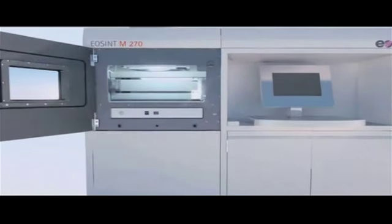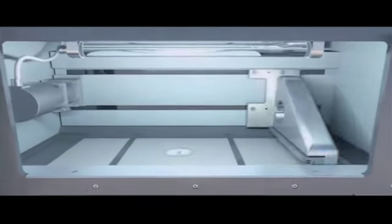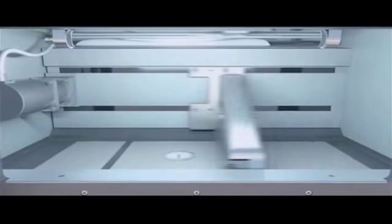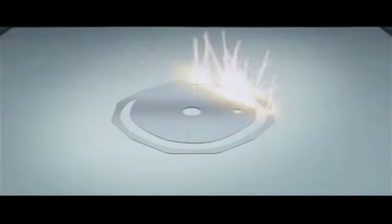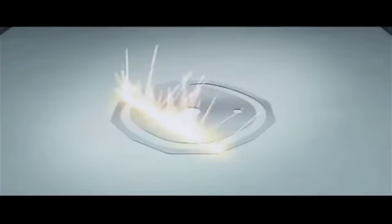It then takes each layer of your design and sends it to a laser that melts powdered metal and contours and fills in that layer of powdered metal as per your design. Now, continuing this process layer by layer, it may take only a couple of hours, or it may even take a couple of days, but layer by layer, you can actually get a fully three-dimensional object to grow.